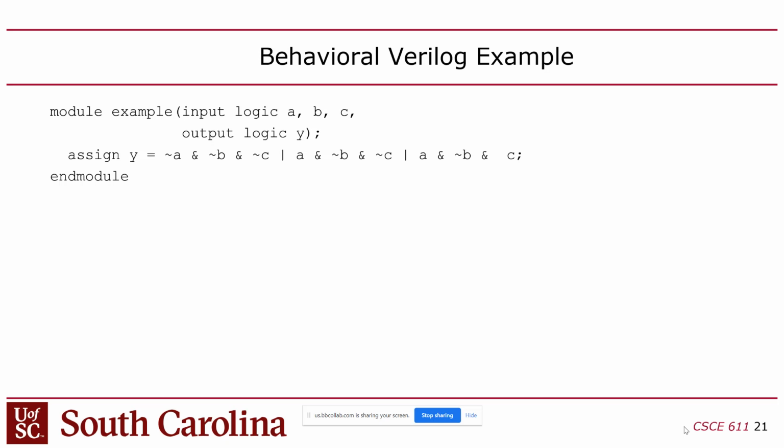Now, it may not change Y, because there might be a change in one of its inputs that doesn't cause the output to change, but it's still going to do that. So, for example, if you had a circular dependency in here, like if one of the inputs was also the output, you'd end up with a cycle where I change something here, which causes a change here, which then triggers that, which updates that, and then triggers that and updates that. What ends up happening is the simulator will literally freeze. ModelSim will freeze. And the problem with that is you'll have no idea why, because it's hard to track those down.